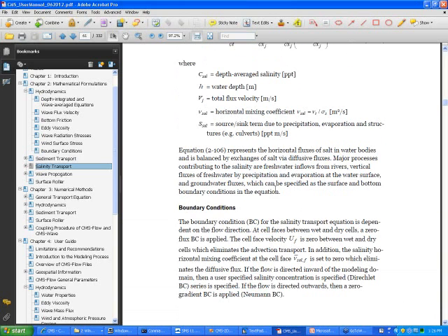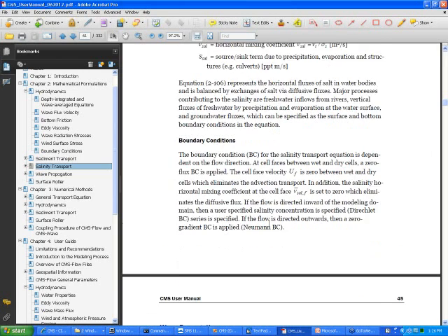You just basically turn it on, specify time step, and the only other parameter you need to specify in the model control is the initial condition. And that is given as a spatially varying data set or a constant. And at every cell string in the model domain, you need to also give a time series for the salinity, and it's constant for that whole cell string.